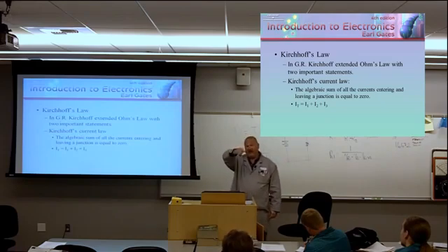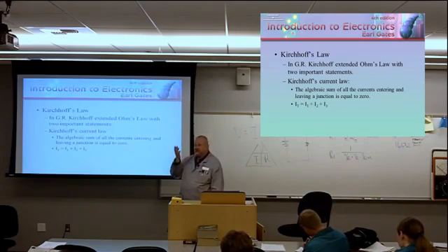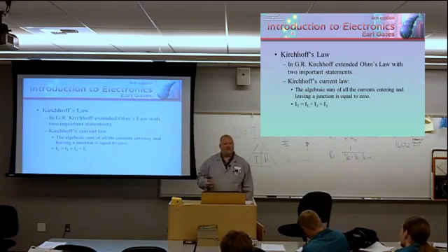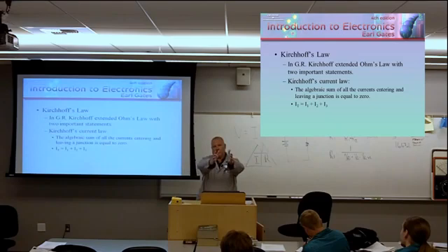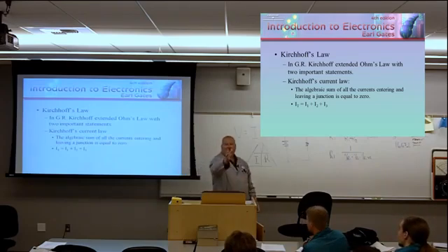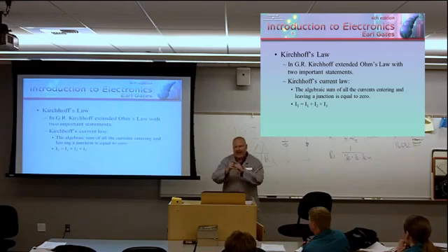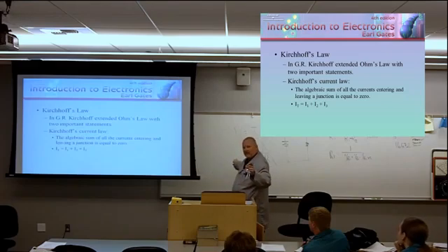That's what Kirchhoff came up with, and he made the textbooks. You laugh. His name's in the textbook. My name's not. That's Kirchhoff's current law. What Kirchhoff is saying is that the total current entering has to exit. And it's really a profound troubleshooting tool. Because I say, I've got 3 amps of current flowing at me, and I've got 8 amps flowing away from me.